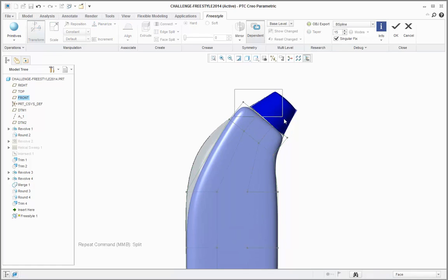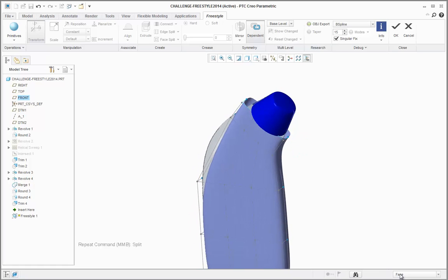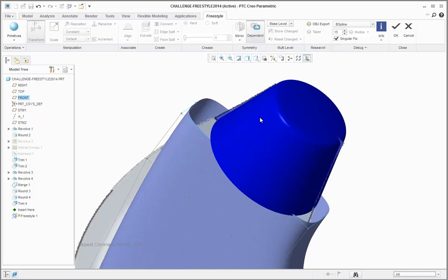We want the bottle to attach smoothly to the cap. To achieve this, we need to create an opening in the geometry. Orient the model to the front view. Box select the top faces of the control mesh. Then either press Delete or right mouse button and choose Delete. Change the selection filter back to All and pick the entire chain of open edges.